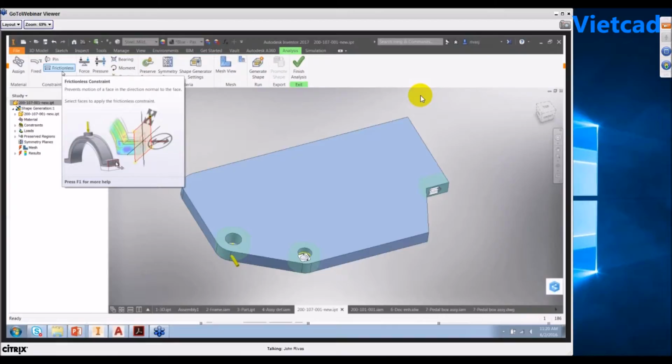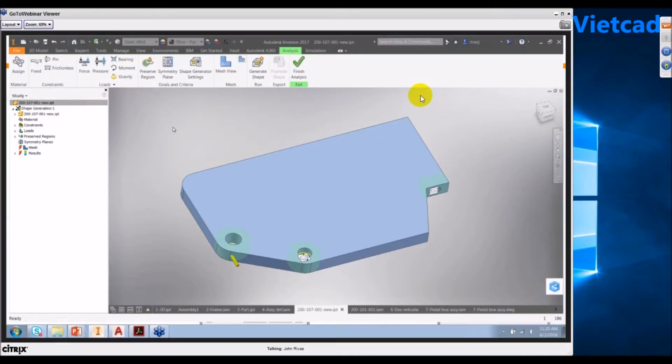And last is the boundary conditions, wherein you specify where the loads are and where the constraints are. Very simple steps. So from here, I have these loads that have been defined. As you can see here, I have a particular 1000 Newton load, which is a bearing load. And these are pin constraints, and also if this part is going to hit at a certain location.